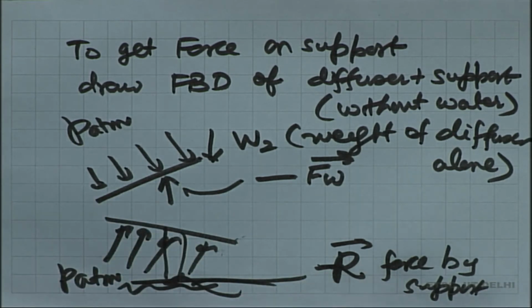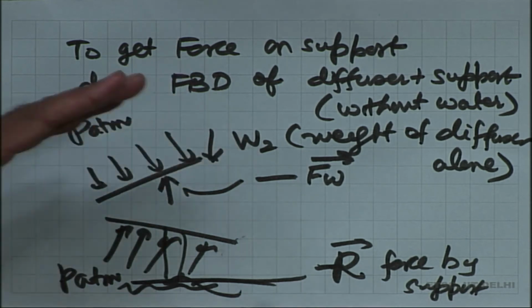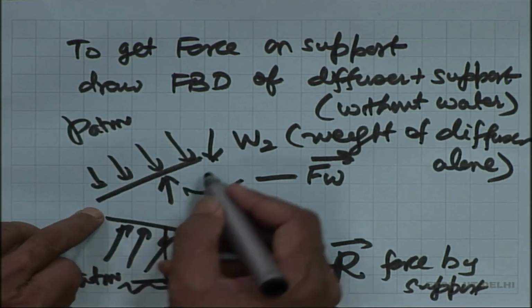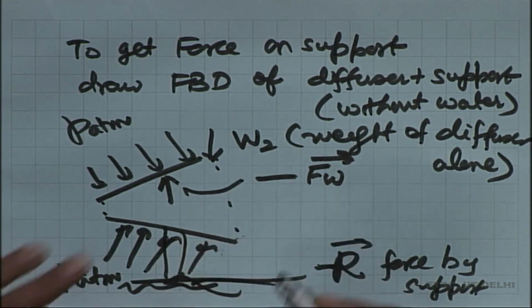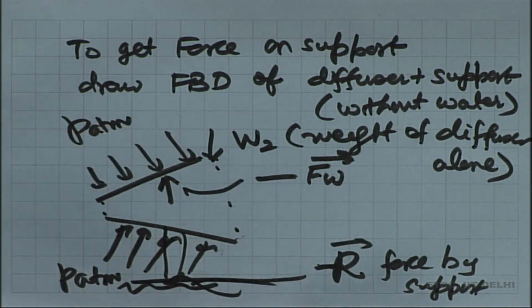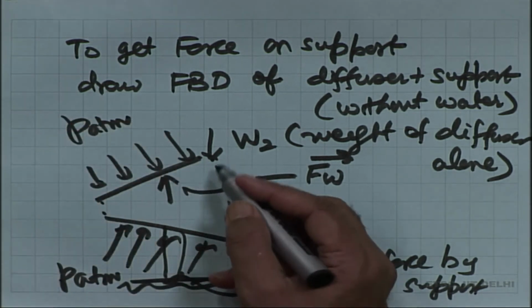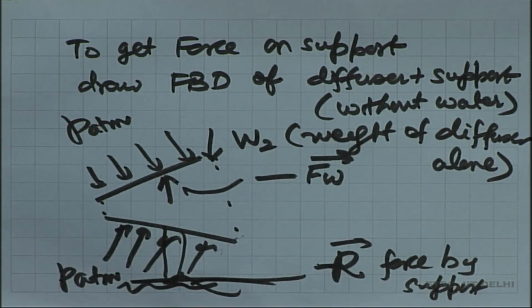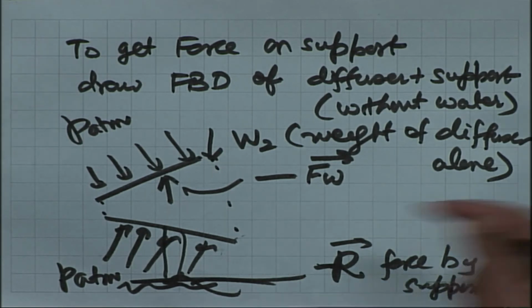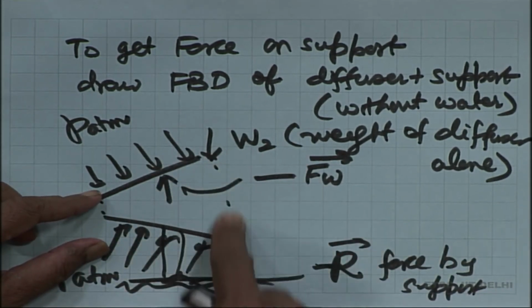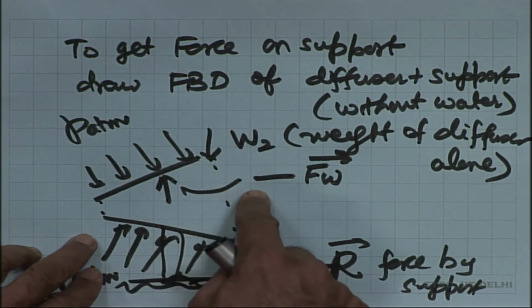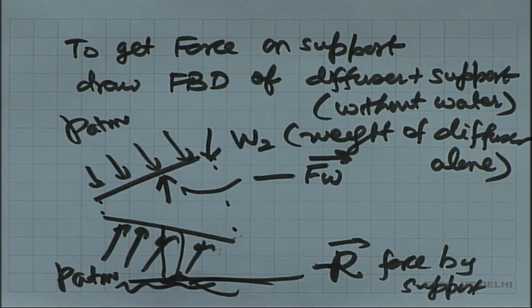And then you do force balance on this, and what you will see is P atmosphere which is acting, because this part has already been accounted for in P1 absolute. So, when this P atmosphere acts, the net effect will be P atmosphere acting on A2 minus A1, because the vertical components of P atmosphere will cancel out, and the horizontal component will give you P atmosphere multiplied by A2 minus A1, and that when you add up,